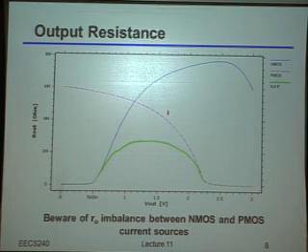So the take-home message here is to make sure that when you are characterizing these amplifiers, when you're trying to design for a certain spec, you pick off independently the NMOS versus the PMOS section, so that you can have an idea of which one really is dominating more heavily in terms of the actual swing range you're able to achieve. Make sense to everybody?